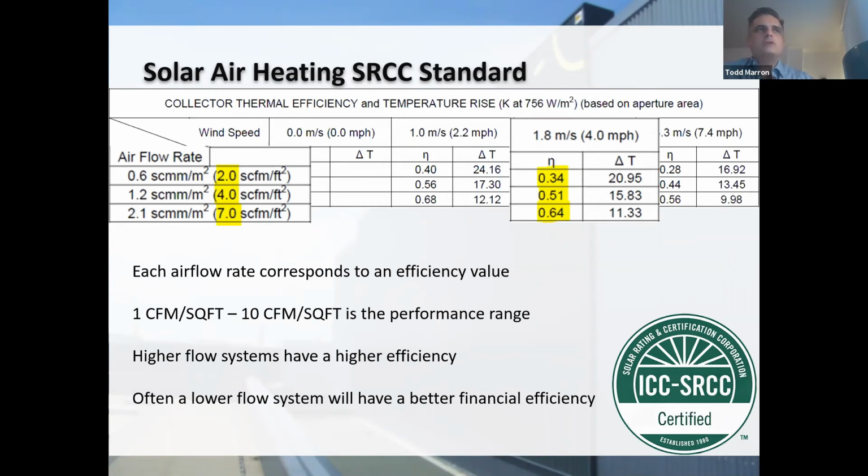So like Andrew had mentioned, the solar wall is this giant metal collector, completely sealed around the perimeter, and it's got 200 perforations per square foot. So it's basically a sunshade all summer long for that south wall. Swift used to quantify it, and it would arrive at about 2% of the savings being a result of the cooling load alleviation.